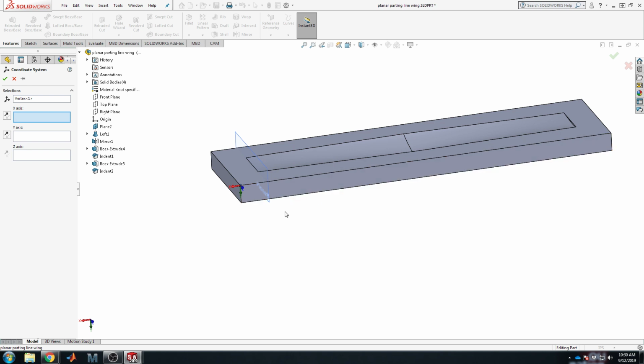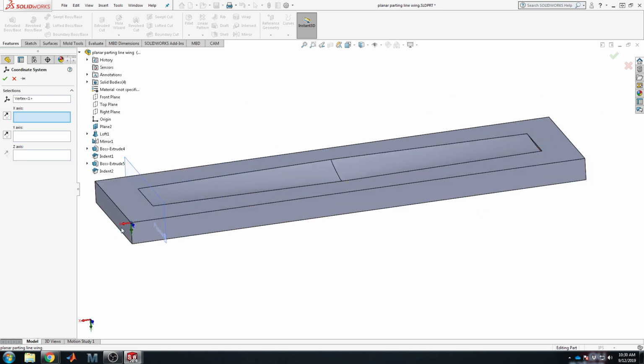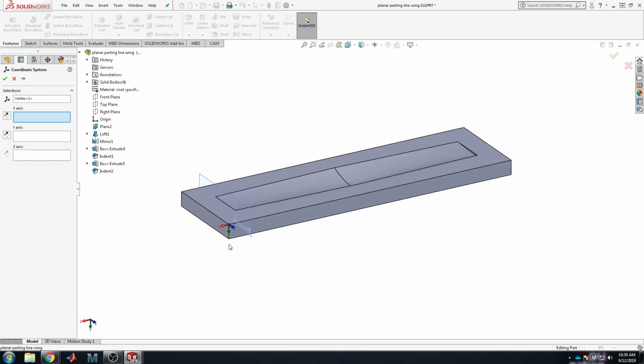You could recess that point at the machine side a little distance, because some of the alternatives is like, well, okay, you could put this point at the bottom, so it's actually at the work table of the machine, and then your code would exist, whatever that is, 2 inches, 3 inches above that origin point, and you'd be cutting everything there. But then if you want to adjust really the thickness of the mold or compensate for any sort of surface defect, you have to go back and regenerate your code and some other things. I don't know. There are a few reasons that I like doing it on the top surface, and none of them are all terribly compelling or important.